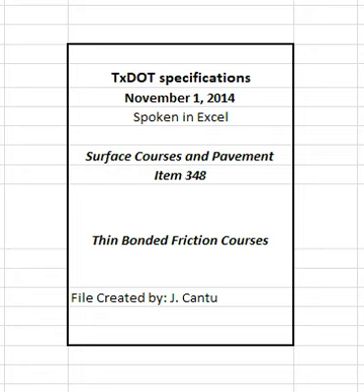The engineer may determine the gradations based on either washed or dry sieve analysis from samples obtained from individual aggregate cold feed bins or aggregate stockpiles. The engineer may perform spot checks using the gradations supplied by the contractor on the mixture design report as an input for the template.